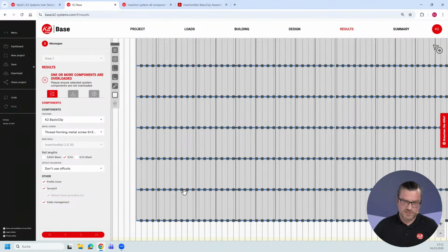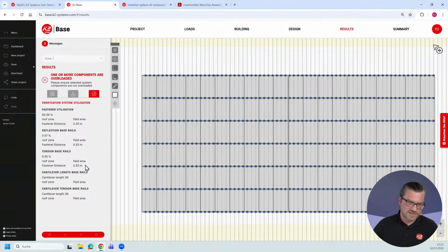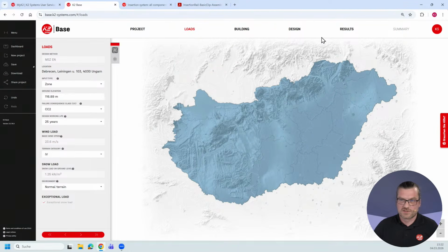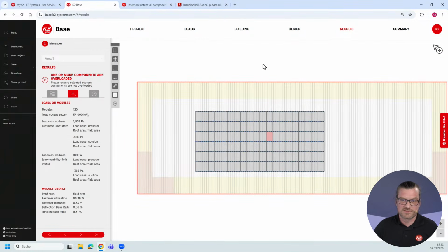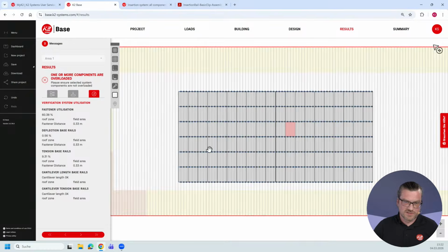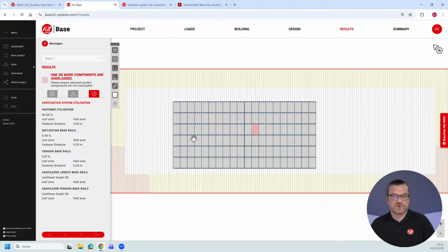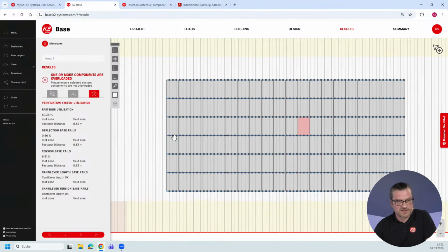So here you have your distance between the basic clips. Here you have it on every crest. Probably reducing the loads, we will get them every second, or maybe not. It's always calculated here. So this is the loads on our basic clips, on our screws, which prevent us from installing the clips every second crest, but we must go with every crest.